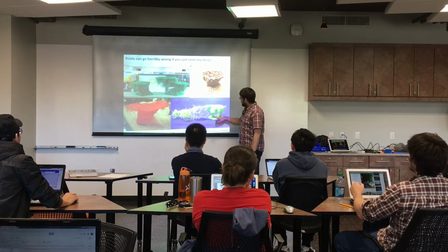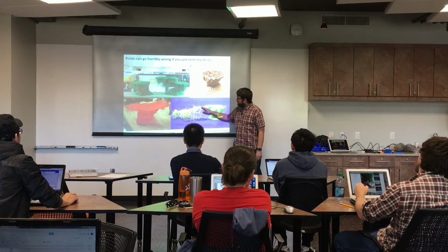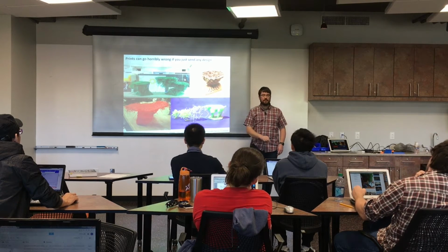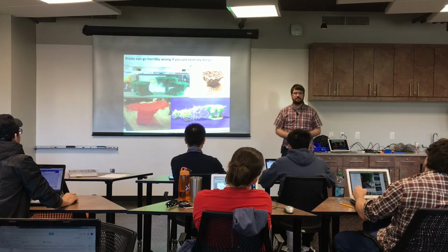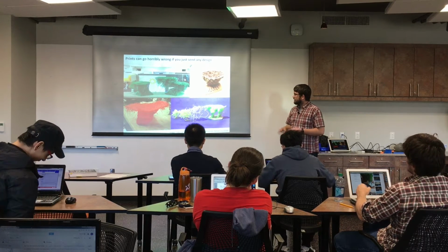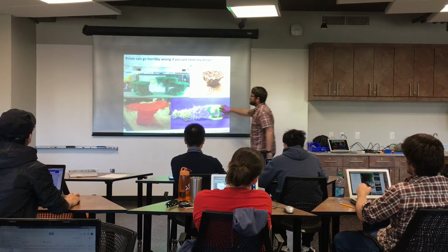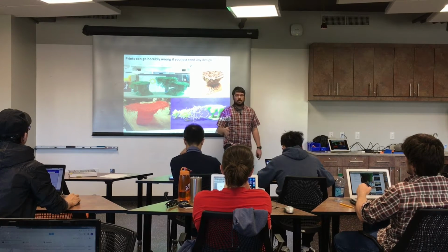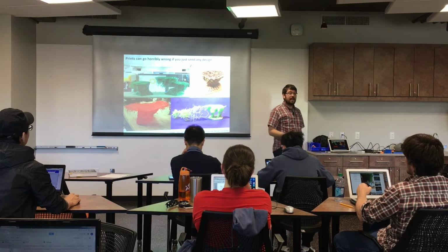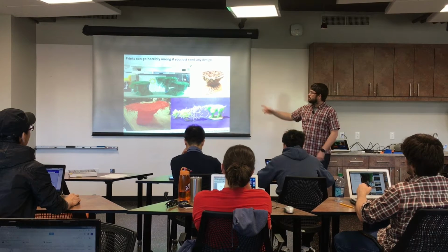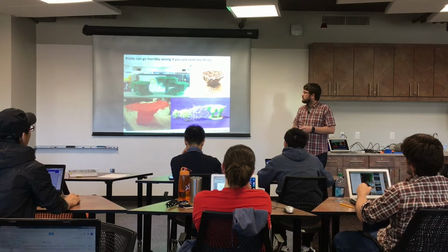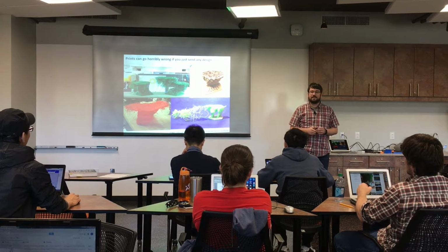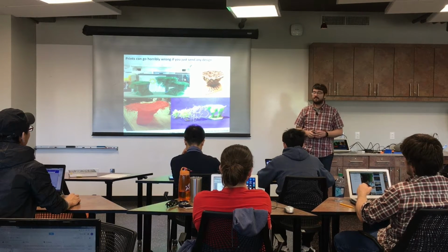Here, whatever this animal was, its head is now strung out because of an overhang problem in the design that was unsupported. And a lot of these parts, something like this life-size head, would probably take 20, 30 hours to print. So the printer had probably already been running for 12 hours when this problem happened. And so that's really unfortunate when you're that far into a large print and something goes wrong.